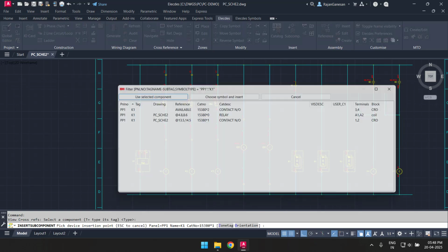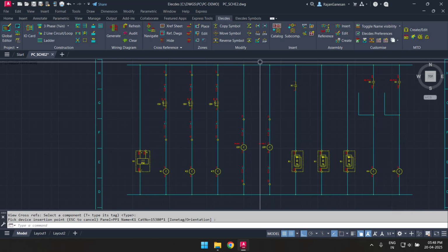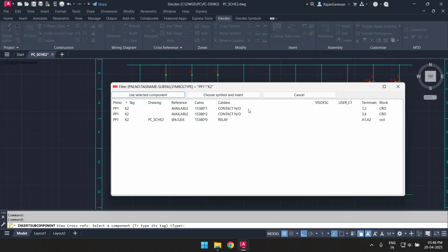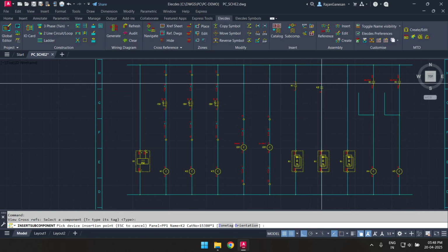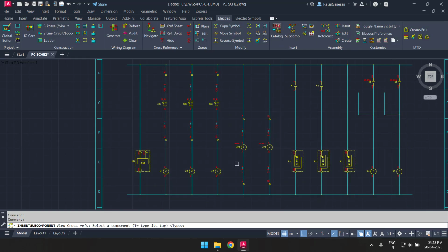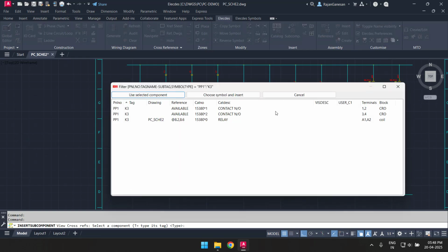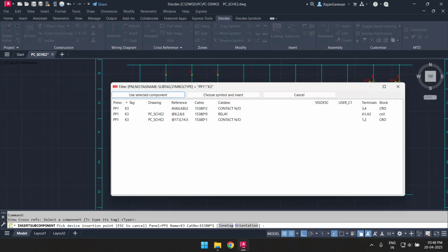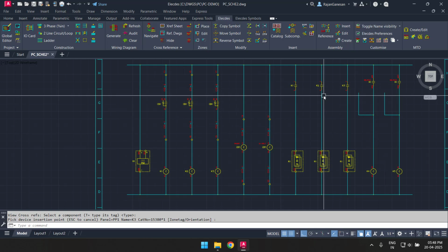Elekta allows me to easily change the orientation, tag name and the spec of any component or group of components. I can easily move components with line breaking and repair being fully automatic in Elekta. I can quickly reverse any component symbol. I can swap a symbol for another symbol by simply dropping the new symbol over the old symbol or by picking a preferred subcomponent from the device.